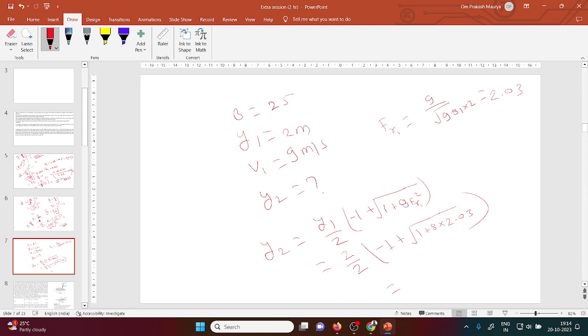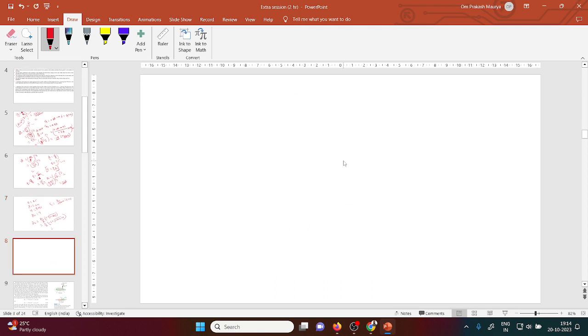Calculate the terminal velocity of a 1 millimeter diameter raindrop falling in still air at standard atmospheric pressure and temperature 20 degrees. The drag coefficient CD is given 0.672.